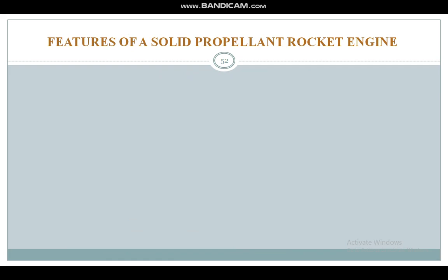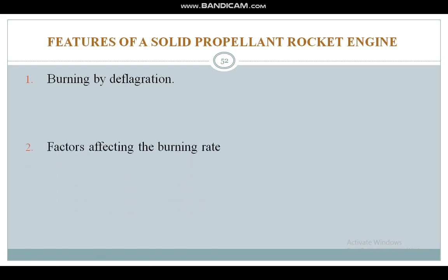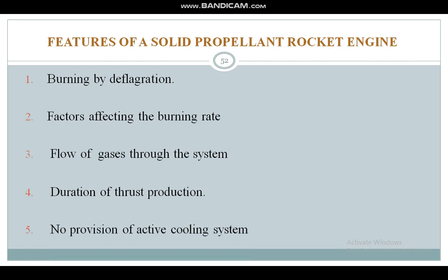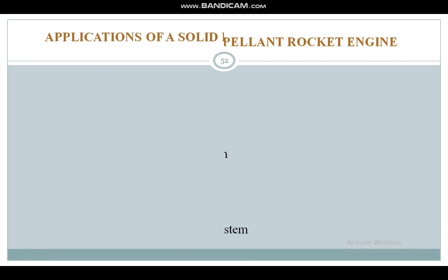After the burning, rapid decomposition causes heat release, and the heat is conducted back to the propellant, and thus the process is self-sustaining. Such a process is called burning by deflagration. So as discussed, the features of the solid propellant are burning by deflagration, factors affecting the burning rate, the flow of gas through the system, duration of thrust production, and there is no provision of an active cooling system.